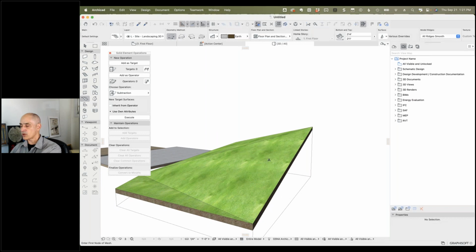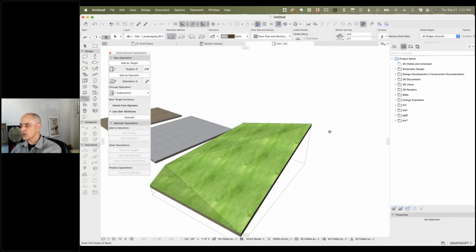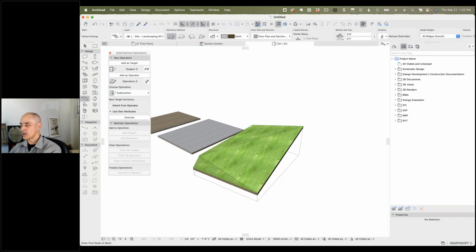So it could be any arbitrary shape of mesh, but it certainly is a very simple way. Just drag a copy of it. Now, the issue is that the copy is not linked to the original. So if you modify the geometry of the upper one, the lower one won't be smart. You'll actually literally have to delete the lower one, select the main one again, and copy it. So it's not updating, but it's very quick to do.